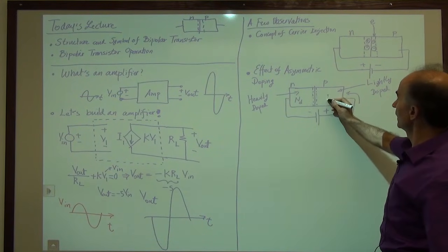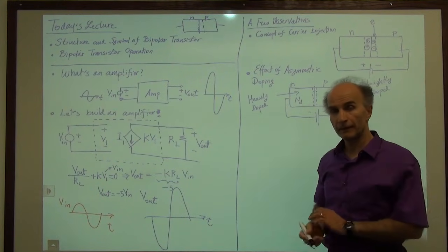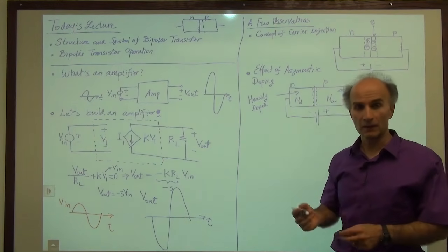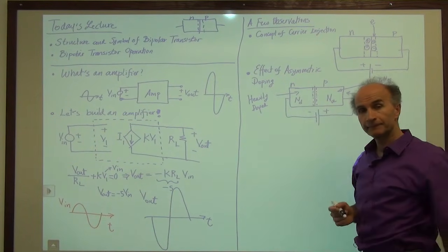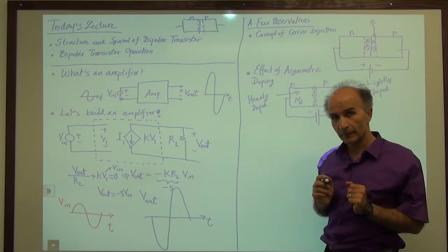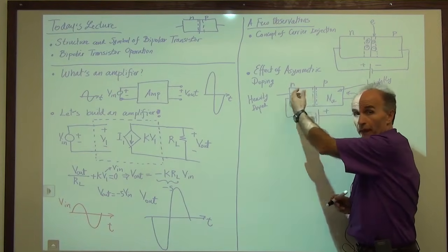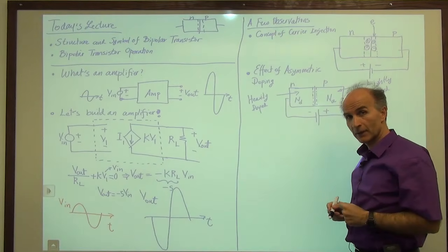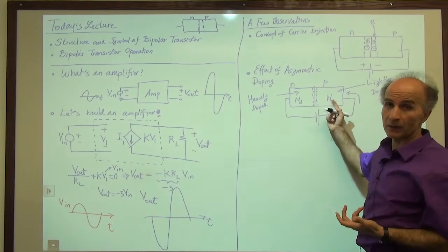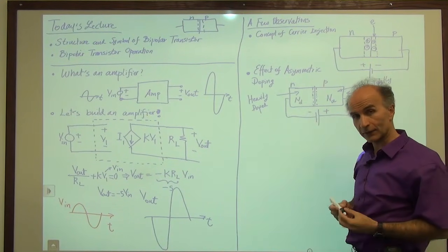And so this would be acceptor density, and the assumption is that the acceptor density is small, maybe 10 to the 15. So maybe this is 100 times this, right? So then what do we expect? Well, we have lots of free electrons here, so they would like to travel to the right and carry the current. But we don't have that many holes here. So we have some holes, and they do carry this way. They go this way and carry the current.